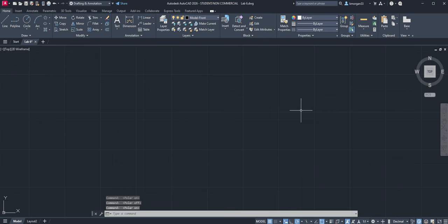Right now just go ahead and turn on the restrict cursor to specified angle, we just do F10 for that. You will see the highlighted blue little icon right there with a circle and 2 lines, so 2 radius. On the status line, you can also see the angles.